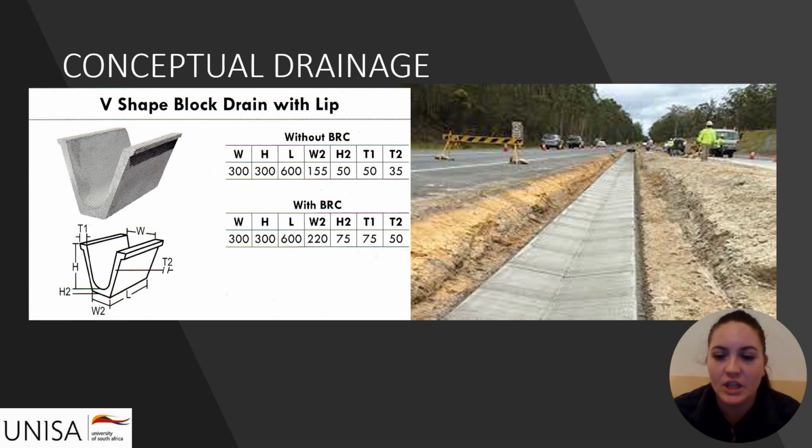The proposed drainage for this project is a paved V-drain along the shoulders of the Rift Valley Road. The V-drain will be placed on both sides of the road, as the super elevation is 2% going down towards this curve. The water will then flow southbound towards the bend of the road into the Lion Pride Lifestyle Estate.